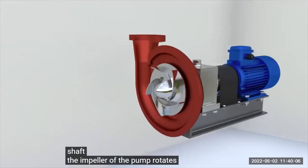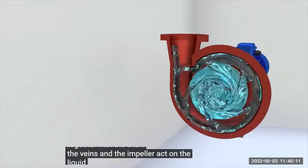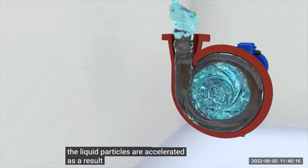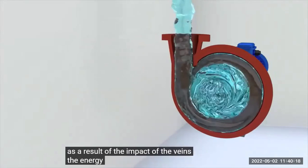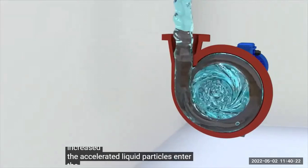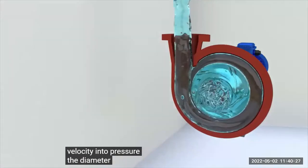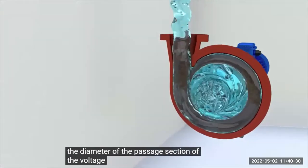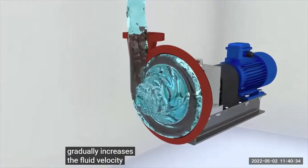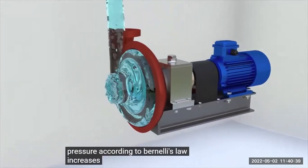The power is transmitted from the motor, most often an electric motor, to the shaft. The impeller of the pump rotates together with the shaft. The vanes in the impeller act on the liquid and make it rotate. The liquid particles are accelerated. As a result of the impact of the vanes, the energy of the liquid flow is increased. The accelerated liquid particles enter the volute, which converts part of the velocity into pressure. The diameter of the passage section of the volute in the discharge nozzle gradually increases. The fluid velocity decreases, and the pressure, according to Bernoulli's law, increases.